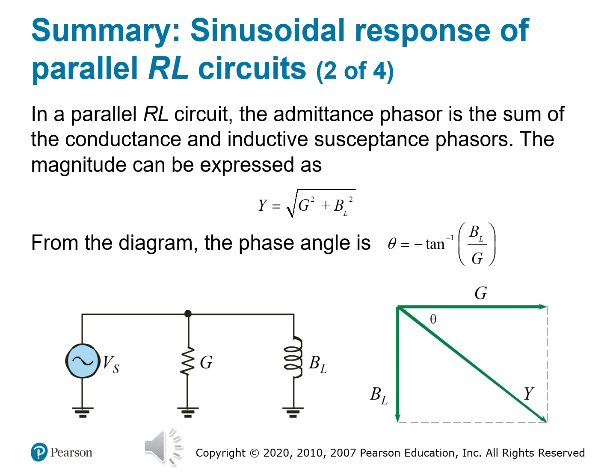Admittance and phase, flipping the triangle for parallel RL. So in a series RL circuit, we analyze opposition using impedance, denoted by Z, and its triangle. But in a parallel RL circuit, the game flips. We now work with admittance, which is the reciprocal of impedance, and its triangle is built from conductance, denoted by G, and inductive susceptance, denoted by B sub L.